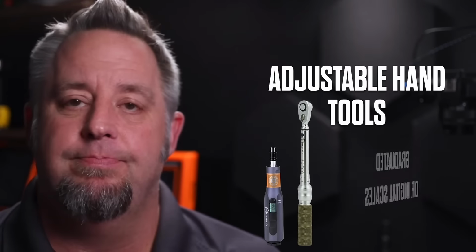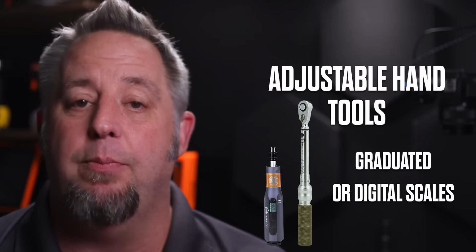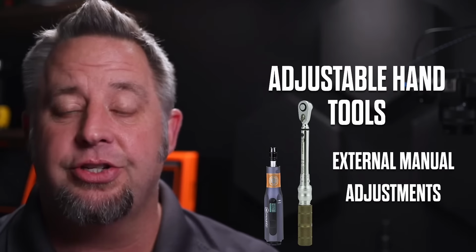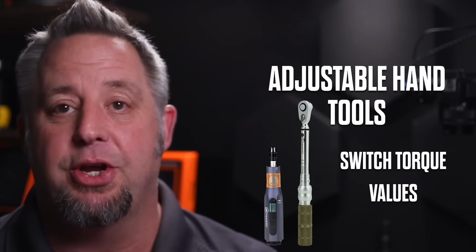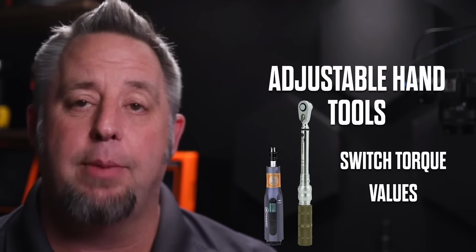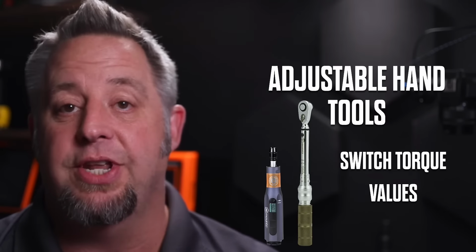Adjustable tools, obviously, are adjustable with a graduated or digital scale that gives the operator the opportunity to externally, manually adjust those tools to a specific torque value. These can be good for switching between different torque values that may be needed for a specific application or series of steps within a certain cell build or part of the assembly process.